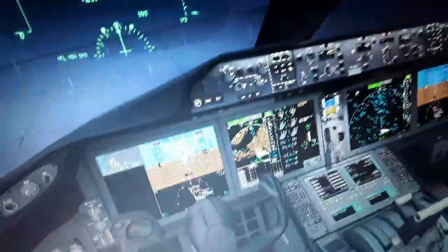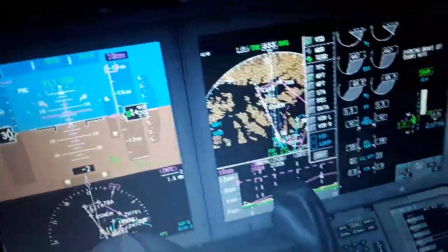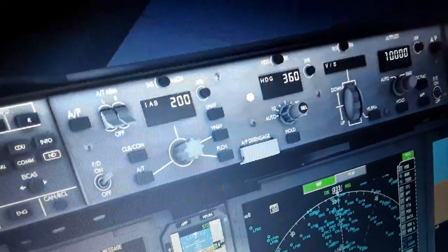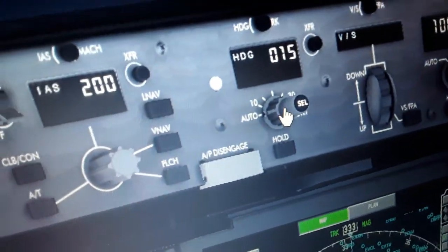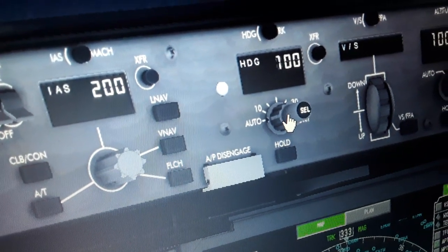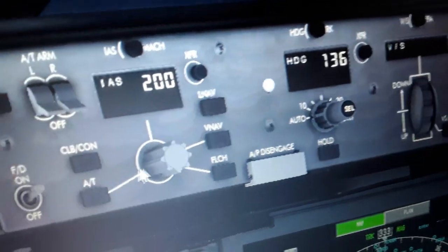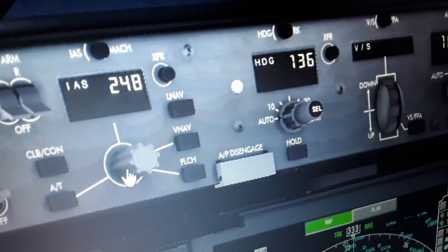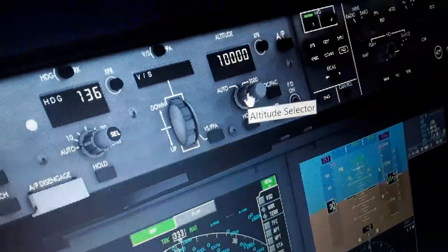So you can see we have the flight plan now created over here. You can see the route over here, also the autopilot flight director system panel. We're going to set heading 360 degrees for takeoff, 136 the runway heading, the altitude over here, the airspeed and the altitude. I'm going to set later if we need, no problem. So we set like 35.